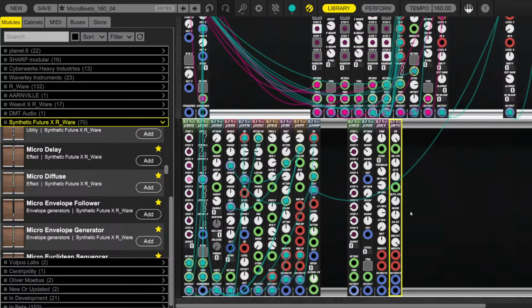And it works more like an actual ADC in this case, because we have the anti-aliasing filters and the anti-imaging filters. The anti-aliasing filter is before everything, so before the sample rate gets reduced and the bits get reduced, and the anti-imaging filter is afterwards. So these are two extra tools to sculpt your sound, and everything has jitter, and you can also add noise, which is not dithering noise, but it's somewhat similar.